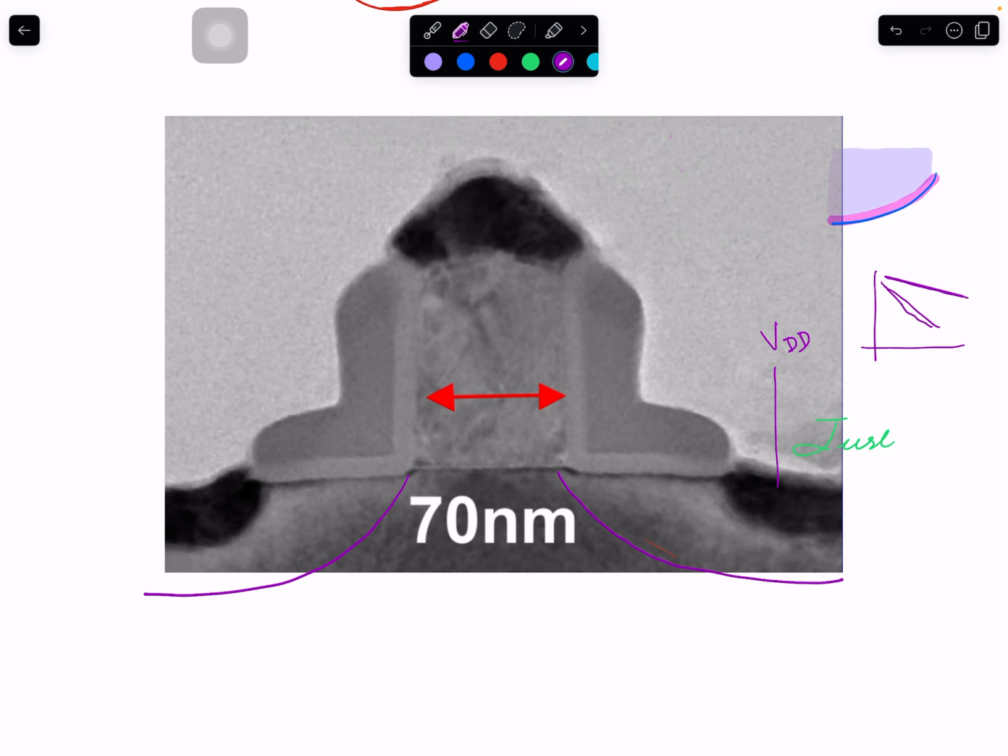So what's the impact? In our good transistor, a nice gate, this is the field that was really more interesting for us when the transistor is off. It doesn't matter how much voltage you apply. All we said is, if the gate to source voltage is not VT or above VT, the channel inversion will not happen here, and I'll talk about it in the threshold section.